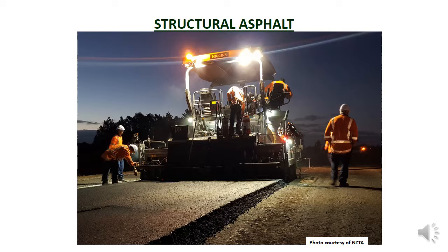Structural asphalt is still quite flexible and not as rigid as concrete slabs, so this type of pavement is often called a semi-rigid pavement. The flexibility means it can tolerate ground movements better than concrete while still providing structural support. The main problem is that it is very expensive. This photo shows structural asphalt being laid on the Hamilton Expressway. Note they are using a conventional paving machine but laying a thick layer of asphaltic concrete.